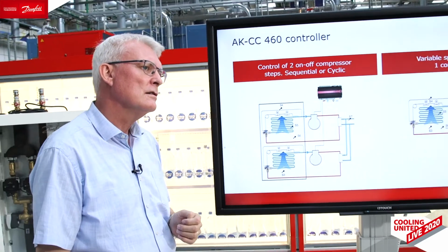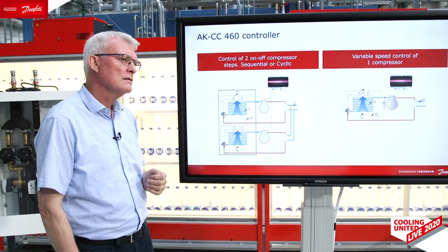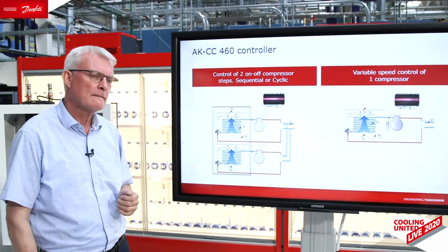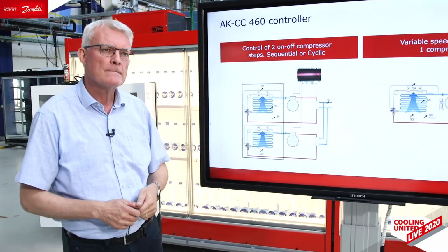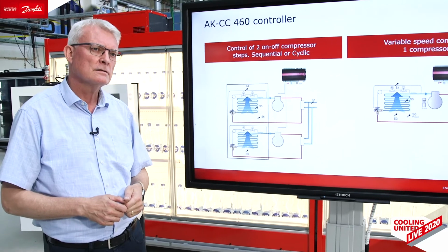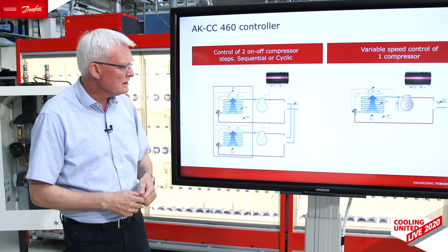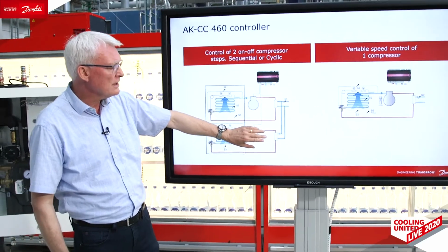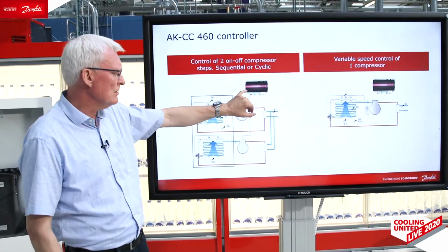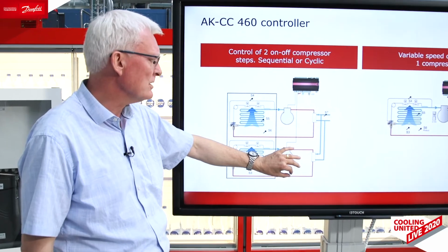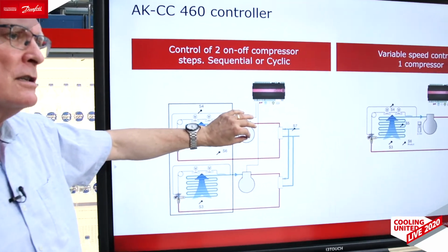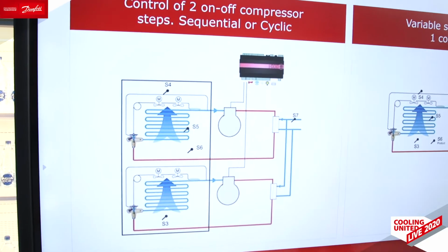Okay, we heard before that Stefan was mentioning that especially for the very large display cabinets we sometimes have 3 refrigerant circuits. Are you able to manage that with these controllers? Yeah, the way we see our OEMs using it is that they have 2 compressors connected to the first compressor output, and then the third compressor to the second output.